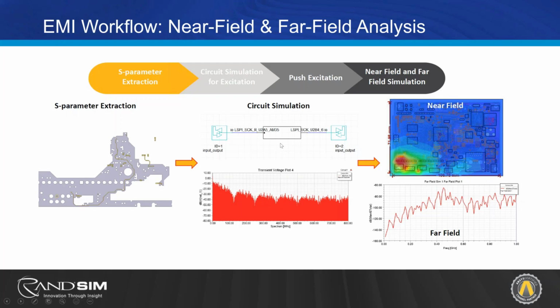And then in Electronics Desktop, you will create a circuit model. What the circuit model is showing is the ports and the source and termination ports of the oscillator. And then in the center, we have imported the SIwave S parameter extraction. So it's a SIwave design. And on these circuit models, these are just IBIS models.